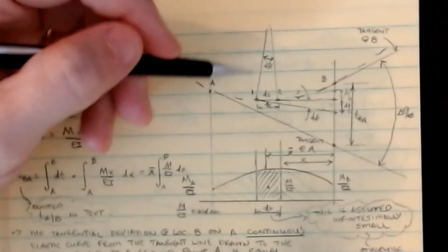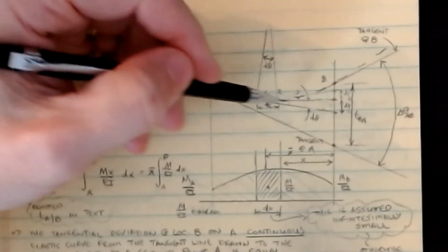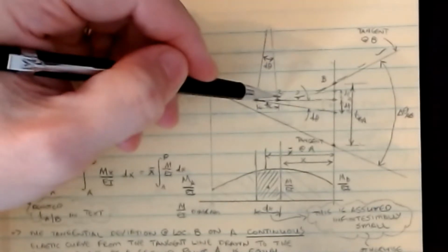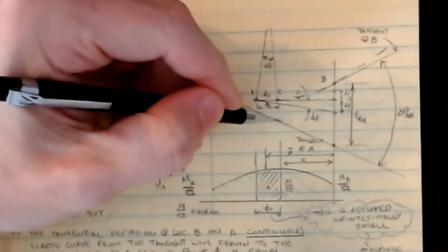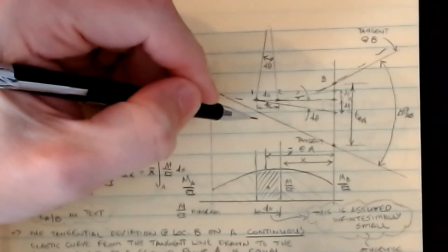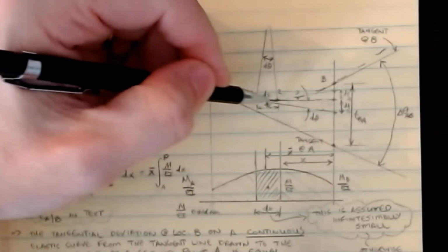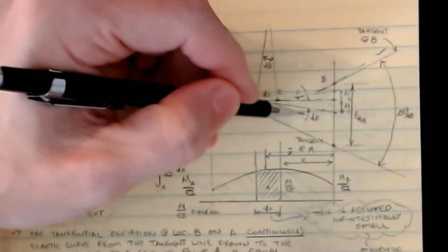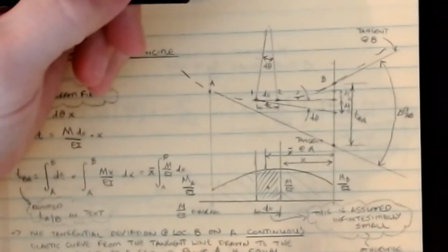I can do some mathematics on this and play with the tangent lines relative to these two points that we chose at the ends. This could be the difference at the ends of a dx element along the length of the beam. If this is the tangent at this point and this is the tangent at this point, then this angle d theta is the same as the angle of the rotation that was here.